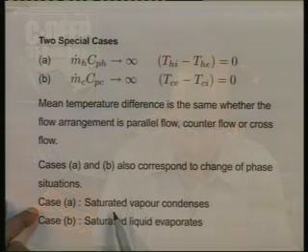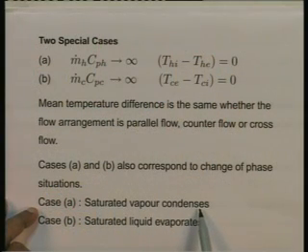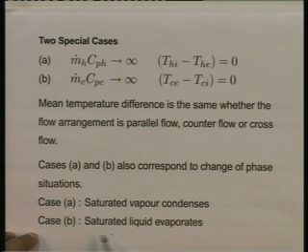The temperature will not change as it changes from vapor to liquid. So, automatically the temperature T s will not change on the hot side. So, case A also corresponds to a saturated vapor condensing, and vice versa case B corresponds to a saturated liquid evaporating.